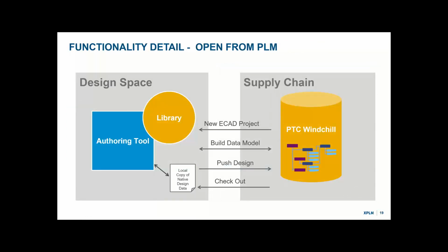Now, whether you're on electrical or electronic, and you want to open a design out of PLM, let's say you're back from two weeks vacation and you need to open a design as an engineer to work on, or it could be two years later, an ECO, engineering change order, on an old design, where you need to make some changes. So you need to bring that design back into CAD. Where do you want to get that design from? Bob's C drive, or the version controlled information inside of your PLM system that's your source of truth? Hopefully it's obvious the latter is the right answer.